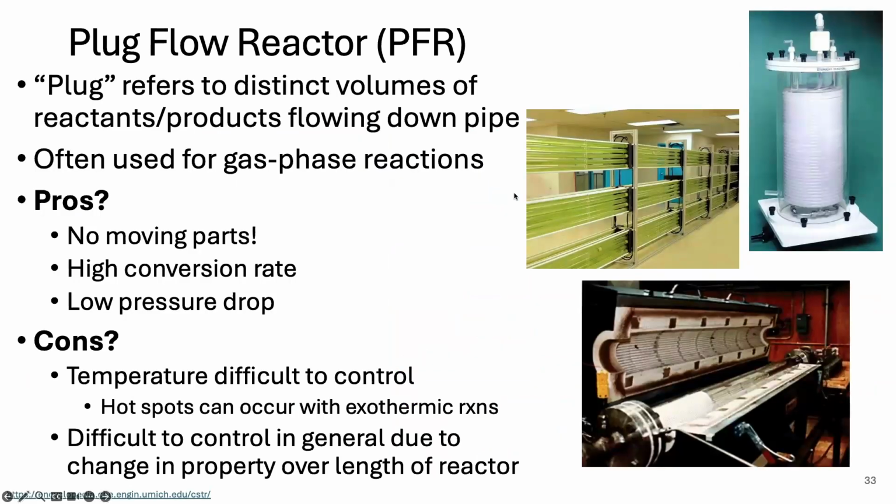So when are PFRs used? Oftentimes we'll use them for gas phase reactions because less mixing is required. And they have several important advantages. First, as was already mentioned, they have no moving parts. There's no stirring, less things to break, lower energy costs that way.